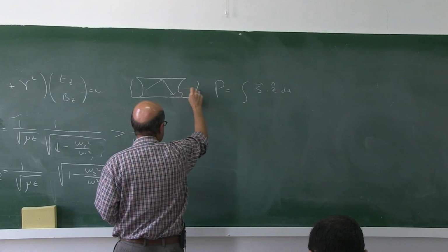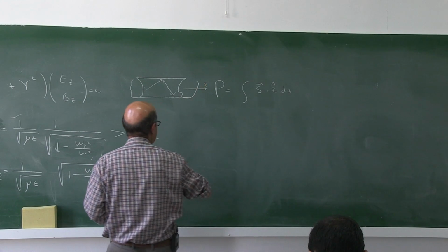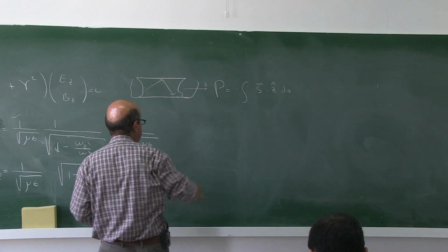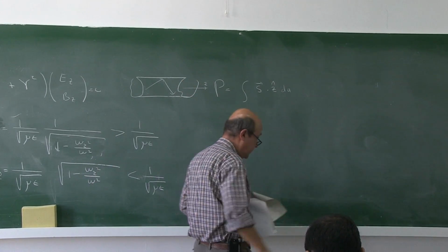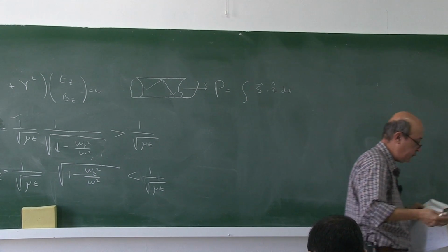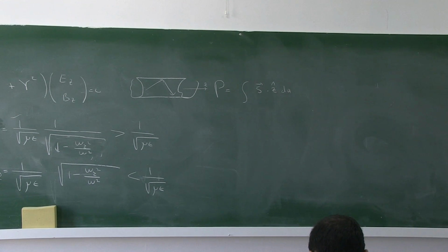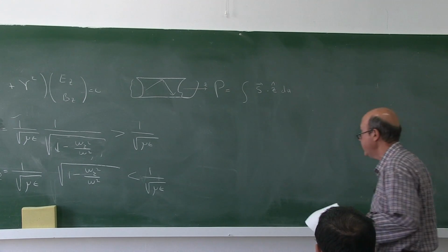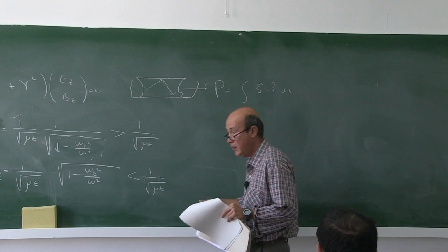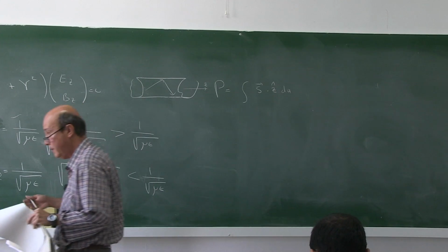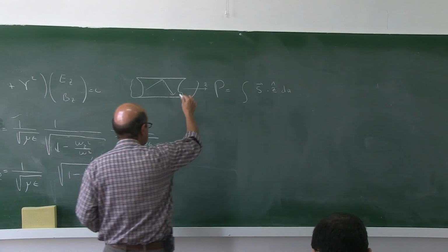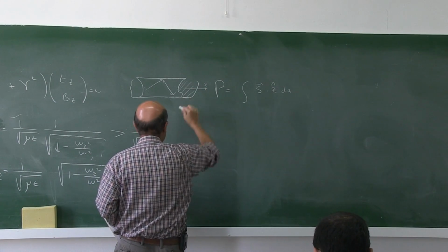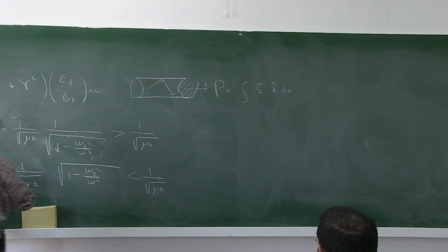So here, this is the z-axis, and we have x, y, and z. S is the Poynting vector, energy per second per area. If you look at the projection along the propagation and integrate over the cross-sectional area, you will get energy per second, and that is the transmitted power. And the transmitted power travels at the group velocity.